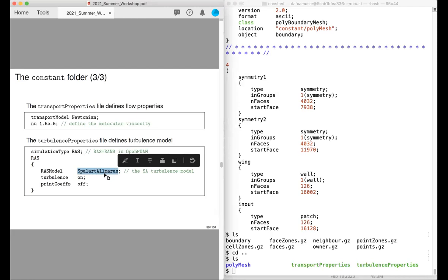Yes, that's a dummy turbulence model. Basically, it's a laminar model. It will not add any turbulence viscosity in the flow. All right, hopefully this will reproduce the inviscid simulations. You need to check that out. We have not gotten a chance to check that, but this should give you the inviscid flow.